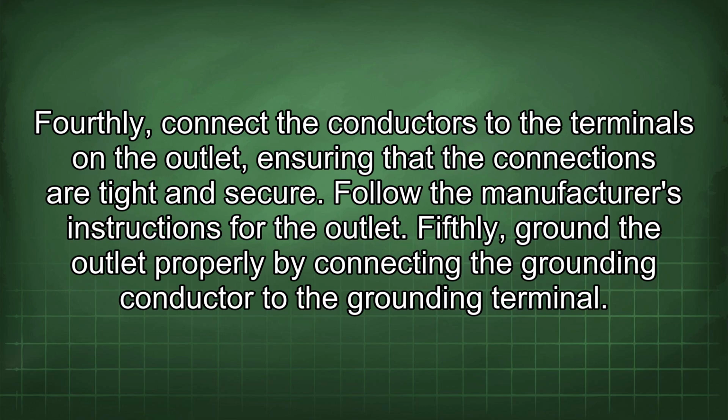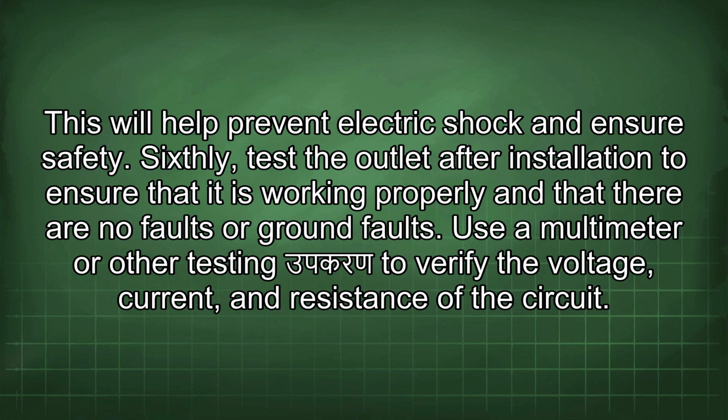Fifthly, ground the outlet properly by connecting the grounding conductor to the grounding terminal. This will help prevent electric shock and ensure safety. Sixthly, test the outlet after installation to ensure that it is working properly and that there are no faults or ground faults. Use a multimeter or other testing applicator to verify the voltage, current, and resistance of the circuit.